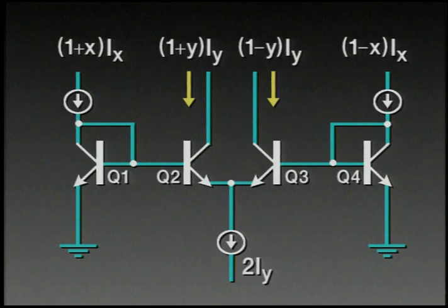And that just means that we have effectively changed the value of the bias current Ix, which doesn't change the relationship between X and Y. It's a kind of a hokey circular argument, perhaps, and it doesn't take more than a couple of lines of algebra to prove for yourself that no matter what beta is, the modulation index at the output is independent of the base current.